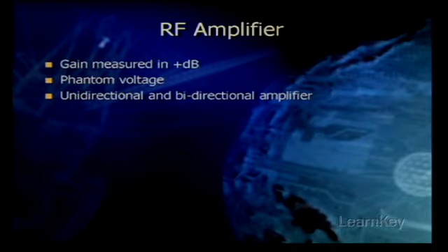Bidirectional amplifiers should always be placed as close to the antenna as possible so as to effectively compensate for any cable loss between the antenna and the receiver. Most amplifiers that are used within a wireless LAN are bidirectional and are preferred for use because they can boost and clean up weak signals that are coming into the antenna before the signal is passed onto the receiving device.